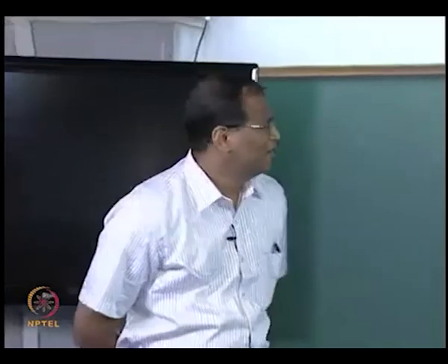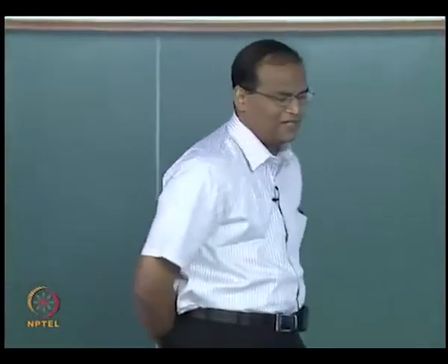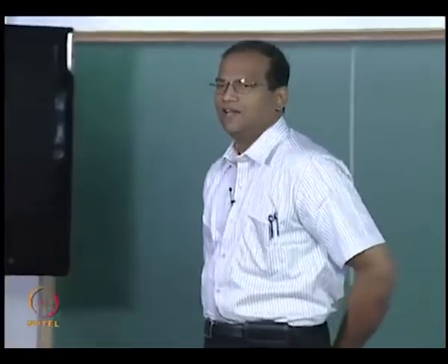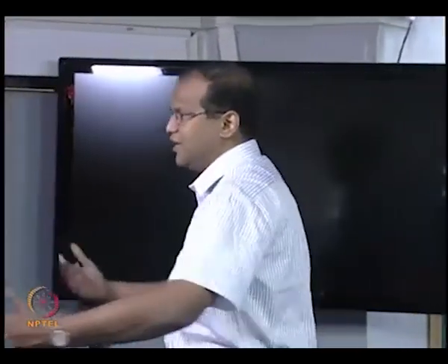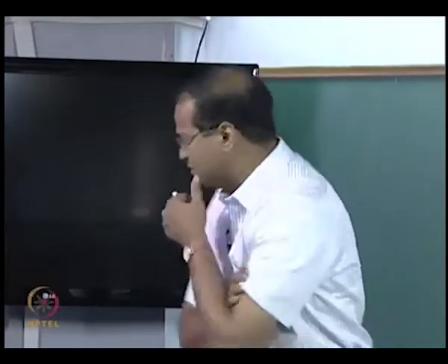Okay, so we will continue with the discussion on radiative surface properties. We have already seen two or three very important properties, namely emissivity and absorptivity. We will have to see reflectivity, and then when you extend these properties to surfaces which are not opaque, that is surfaces which allow radiation to pass through, for example glass or the atmosphere and so on, we have to consider a very important property called transmissivity, right. So first we will look at reflectivity.